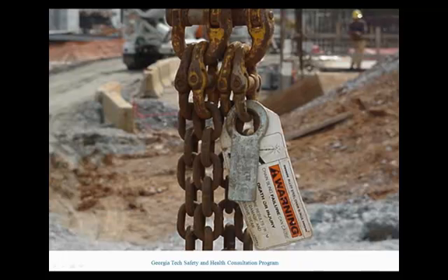When using rigging equipment to move materials, the rigging must be inspected prior to use on each shift, and defective equipment must be removed from service. Rigging must not be loaded in excess of its recommended safe working load, and welded alloy steel chains must have a permanent identification tag stating the size, grade, rated capacity, and sling manufacturer.